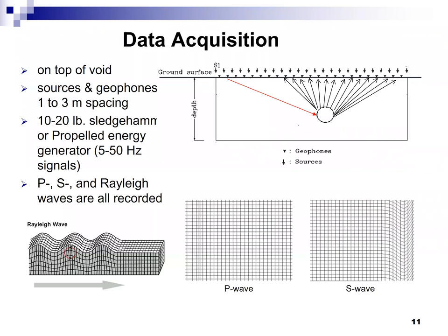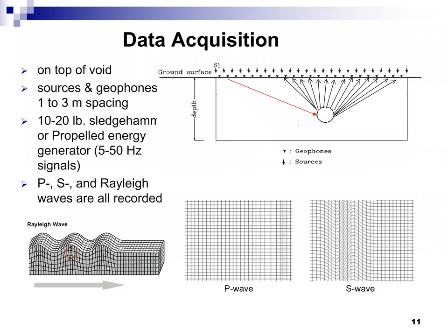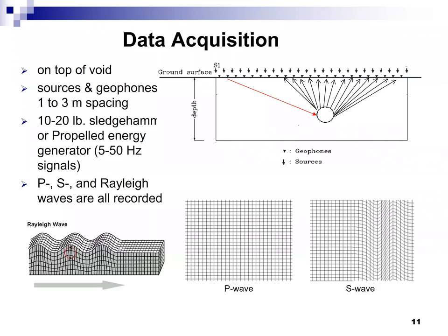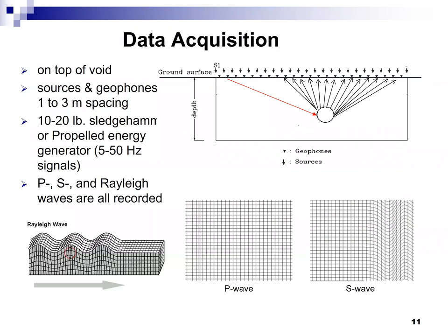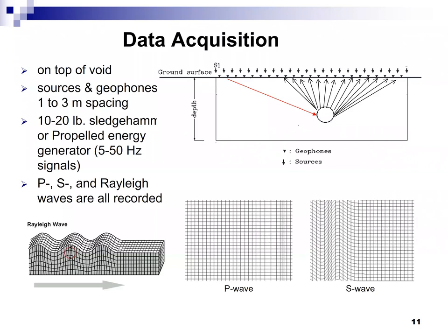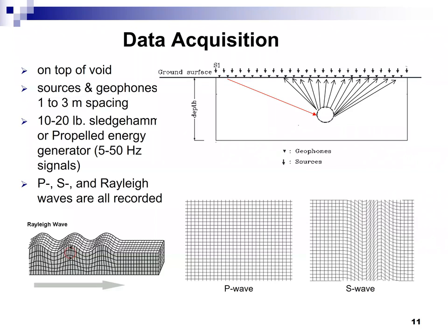Yeah, it's difficult to measure the high frequency component on the ground surface because it's still dominated by the Rayleigh wave. You cannot separate them in the time domain. True. So it's mixed together at geotechnical scales. That's why our scale is more difficult than large scale. We don't have a problem with the computer, but we have a problem with the Rayleigh wave. We cannot separate them.